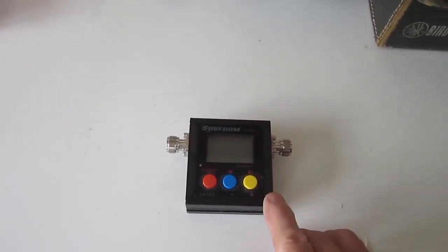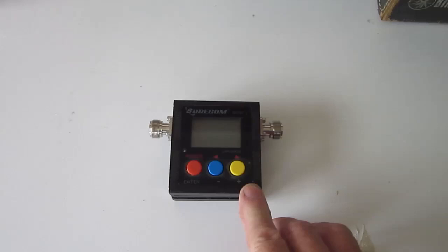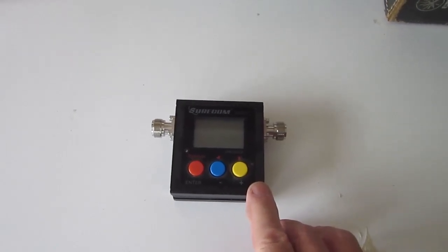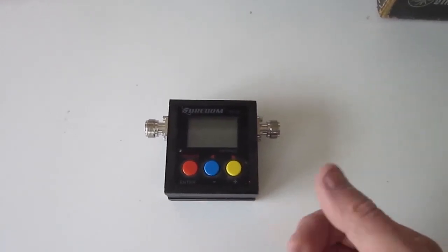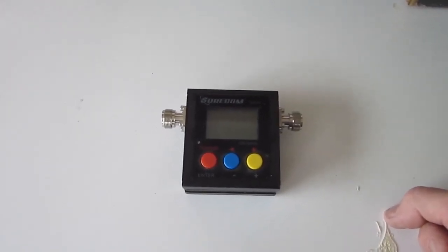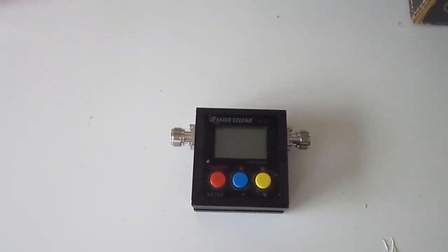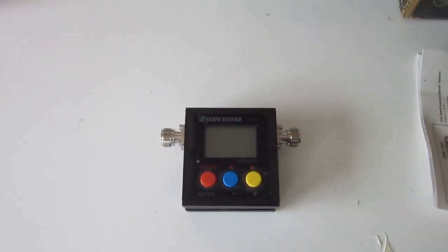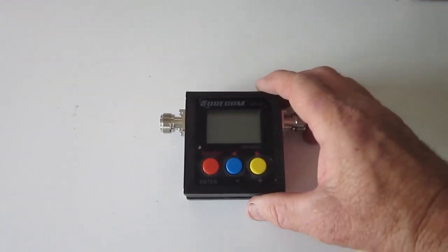This meter gives you an additional reading, which is your transmit frequency. We'll give that to you in megahertz. Very useful if you don't know what your transmitter is actually sending up the aerial. Unfortunately, it doesn't give you forward and reverse power as such. It actually gives you VSWR as a ratio. So if you need to know what your forward and reverse power is, you will need a chart. Now, there's plenty of those charts available online, and it's easy enough to print one off, and that'll give you your forward and reverse powers if you want to know them specifically.